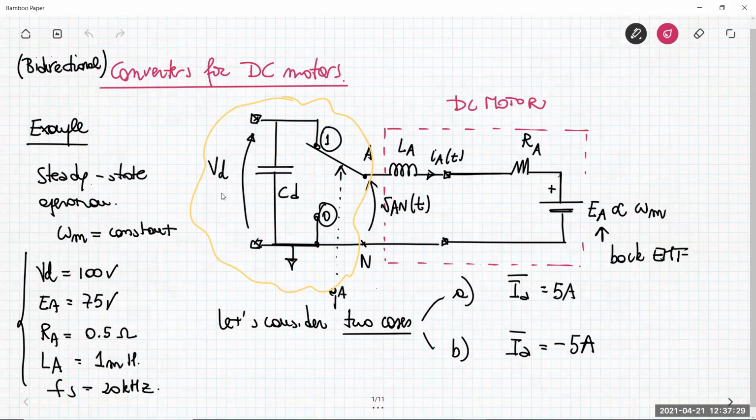Then you use this information as a modulation signal in a modulator, and you transfer your information content into the variation of a duty cycle, which triggers the operation of a switch power pole that produces a distortion in the voltage VAN, and you need to demodulate this highly distorted signal in order to extract the information that you have at the beginning of this channel. Okay, and the demodulator is a low-pass filter.